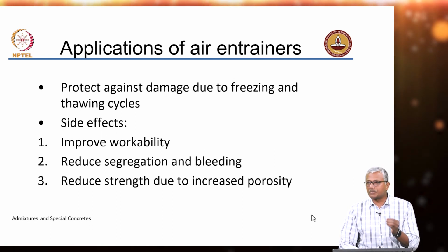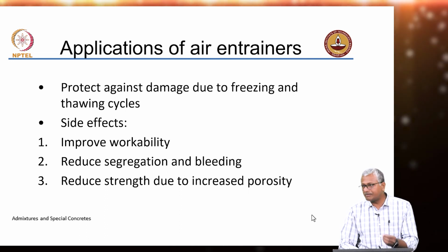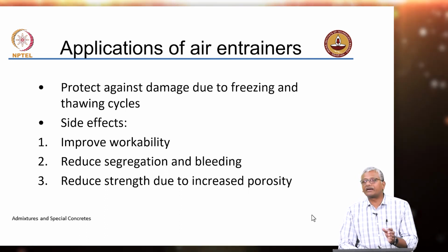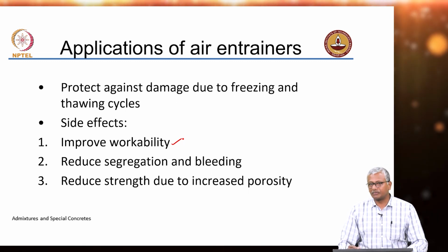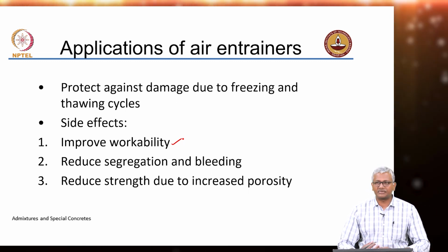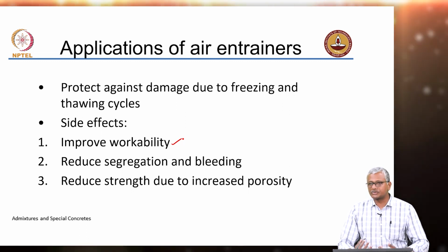Now, because you are putting air bubbles inside, or air entraining agents inside, they also act like ball bearings and improve the workability of the concrete. You will essentially end up having concrete which has a better workability when you use an air entraining agent.